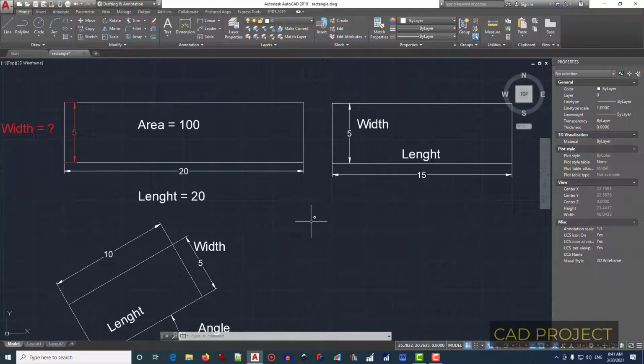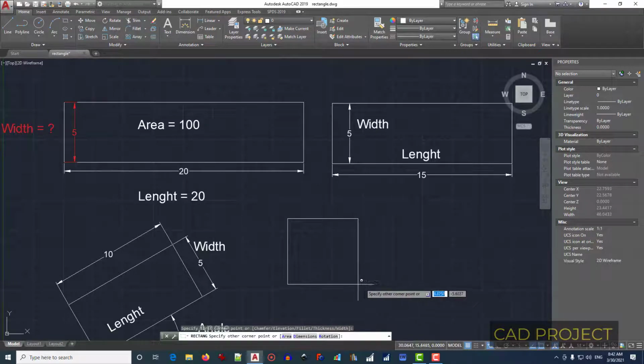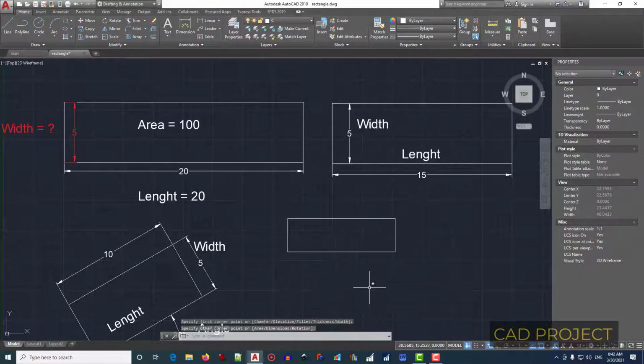The command for rectangle, we find it in the Home menu, in the Draw panel, and there is rectangle, and also we can find here polygon. Now let's focus on rectangle. So click on rectangle and specify the first corner and specify the second corner. Release the mouse button and the rectangle is done. Once more again.